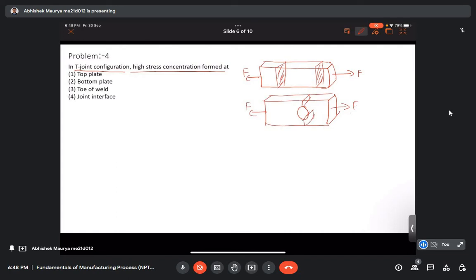So here all the force is getting transferred to very small areas, therefore just at the top point and bottom point of this hole we will get higher stress values compared to, let's say, here, where the stress value is given by F divided by this whole area.